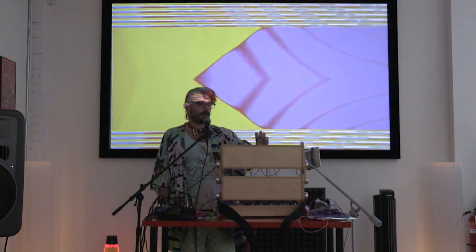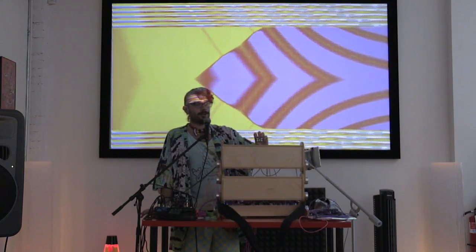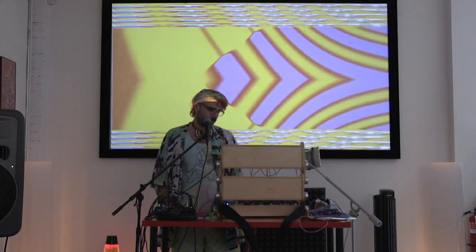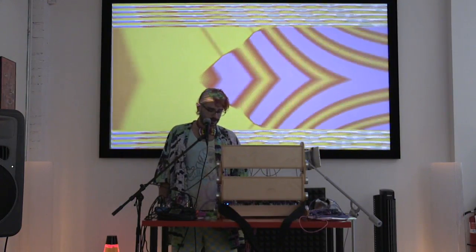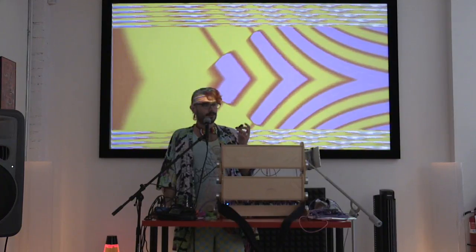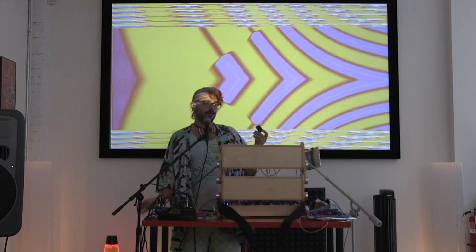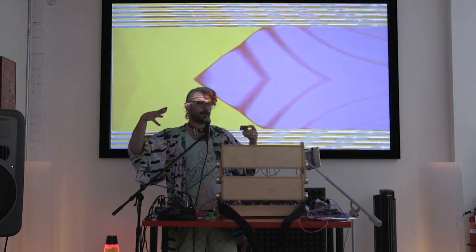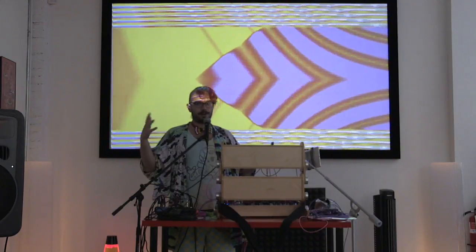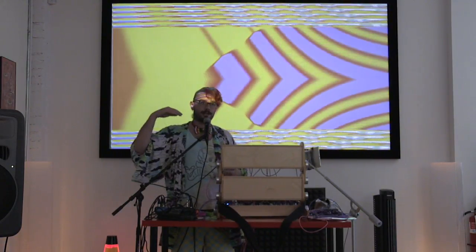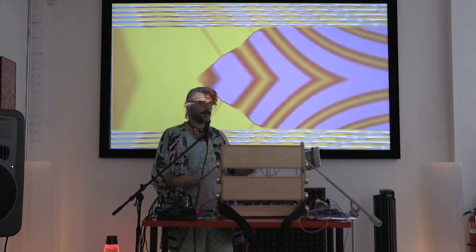We have a filter module, also based on the same chip as the VCA module, so you can do audio rate filter modulation. And our newest 0HP is an envelope, which can be an envelope follower. So if you plug in an audio source like a drum loop or somebody talking, you'll get a voltage which corresponds to the amplitude of your source. So you can use it to extract voltage out of a drum, let's say, and then you're increasing the pitch of your oscillator when your drum is hitting, things along that nature. It also lets you patch in a gate and then you get a normal envelope out of it.